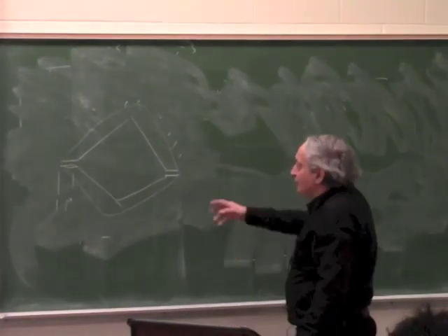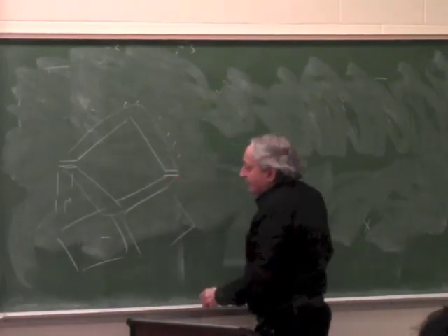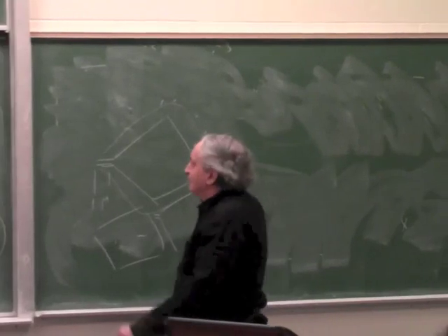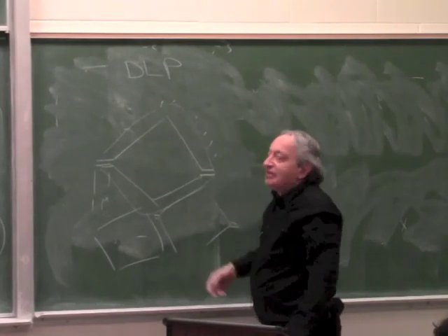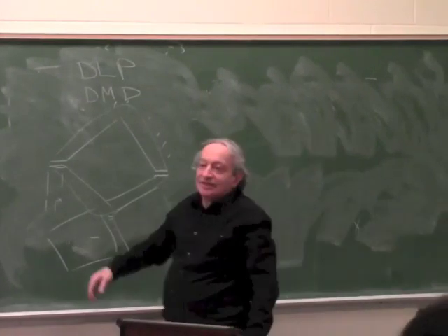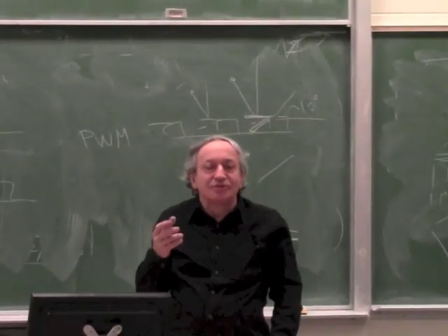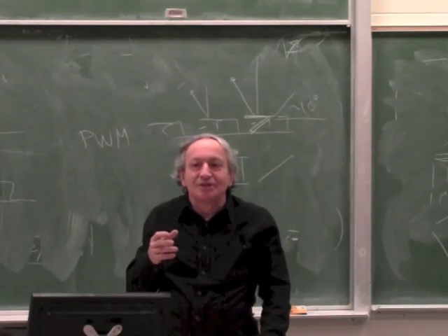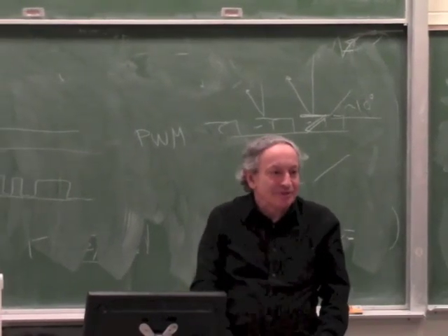Okay? So actually, if you look inside this chip, it looks like this. It's squares tilted at 45 degrees sitting on torsion hinges. There are some pictures on the internet you can see close up. Today it's called DLP, Digital Light Processing. Originally it was called DMD, and it's made by TI. It's quite a masterpiece of micromachining. I would say that's the most sophisticated micromachined part in the world, because it has not only the million mirrors, it has all the electronics to drive it, and a million other things all in the same chip.